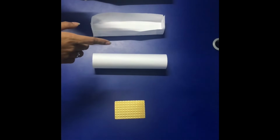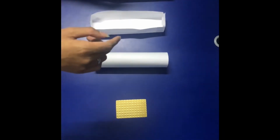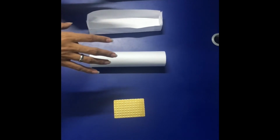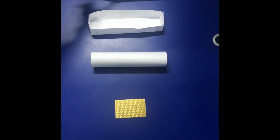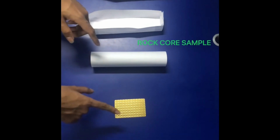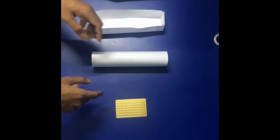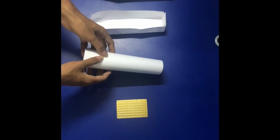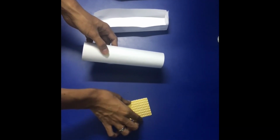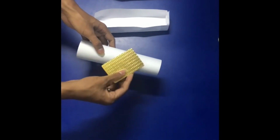Okay, so below are the apparatus that will be used for the experiment, which is the Schmidt hammer, the steel cradle, the core sample, and the sandpaper. Firstly, we need to make sure the rock core sample has a smooth surface, which can be done by using the sandpaper.